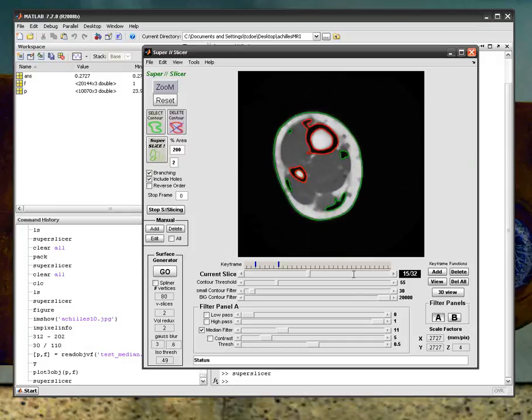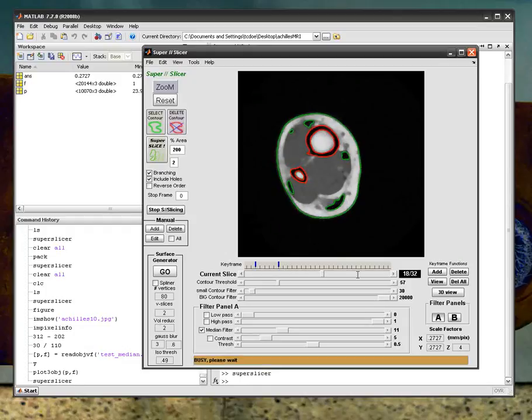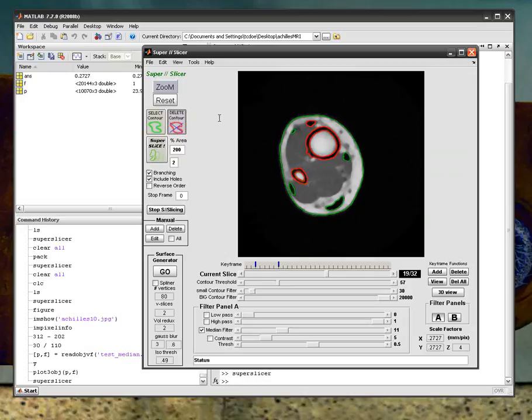Okay, so I've segmented out most of the fibula, and I just want to show you that. Just to remind you that sometimes when you're doing the segmentation, you end up with some objects that you're not interested in. So, for instance, here's an unwanted contour. You have to just delete them manually like this. Okay, and then move to the next slice, delete. Next slice, delete.